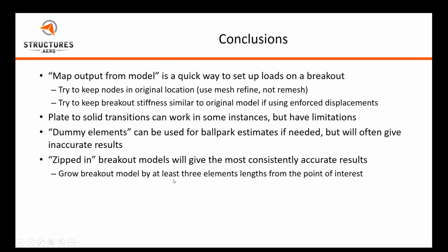So in conclusion, the map output from model is a quick way to set up loads on a breakout. Couple things to look for. You want to try to keep your nodes in the original locations. Try to use mesh refine, not remesh. Remesh will work. It's just, again, you're trading for accuracy.